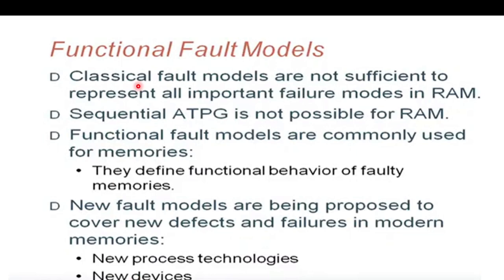So the classical fault models are not sufficient to represent all the important failure models in RAM. Sequential ATPG is not possible for RAM. Functional fault models are commonly used for memories. They define the functional behavior of the faulty memory. What is this sequential ATPG?